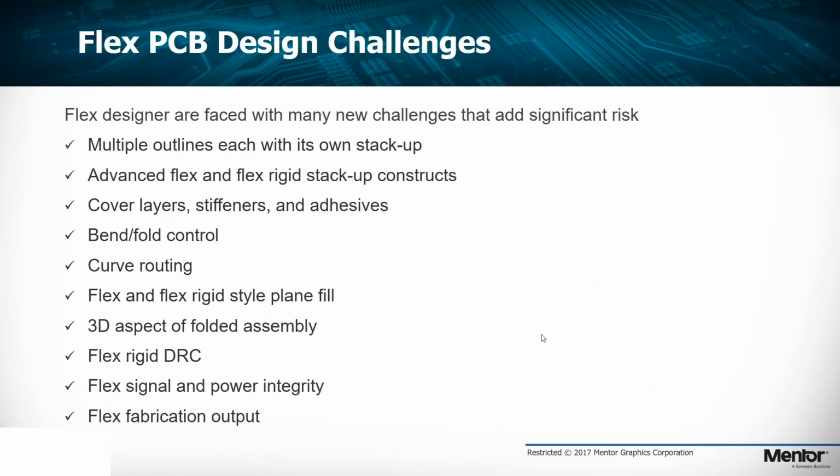So this is just a small example of some challenges of PCB design from Rigid Flex. One of the most difficult things with Rigid Flex in a lot of design tools is how to actually handle the stack up of the rigid flex, because there's going to be a different stack up depending on if you're on different sections of the rigid board. And of course, we're going to have different sections of stack up in the actual flex circuitry as well. So that can cause some major issues, and I'll show how Xpedition is able to make this a very, very simple process to understand a master stack up and assign those accordingly.